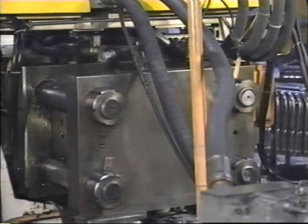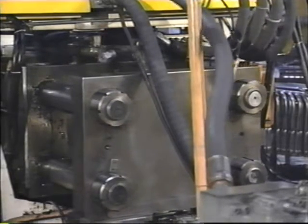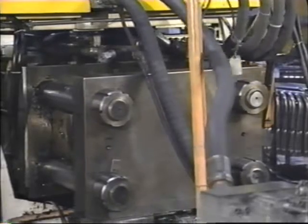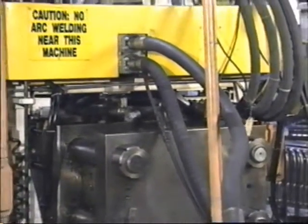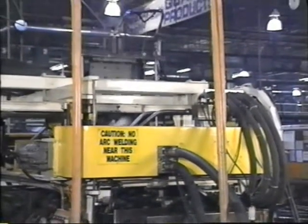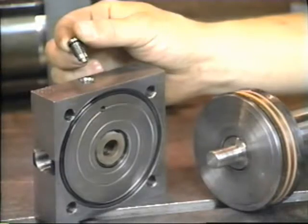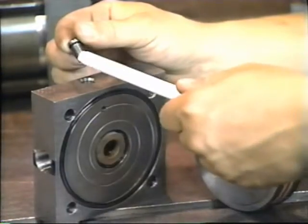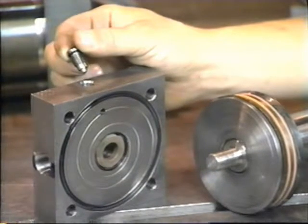Another potential problem with cylinders is hydraulic shock. Sometimes this shock can be severe enough to damage the cylinder. Many cylinders include a cushion to slow down the piston as it approaches the end of its stroke. This reduces the shock and helps prevent damage to the cylinder and the system. The cushion may consist of a needle valve in the end of the cylinder and a plug or spear attached to the piston.